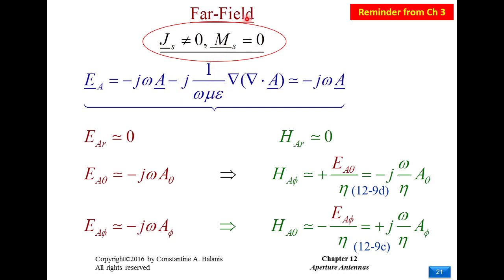And we derived the far field equation based on the auxiliary functions. So we showed that the electric field, because of the A auxiliary function, when we have real electric current, with no magnetic or equivalent current, does have this expression, and approximately it is minus j omega A. And then we did the derivation from A.